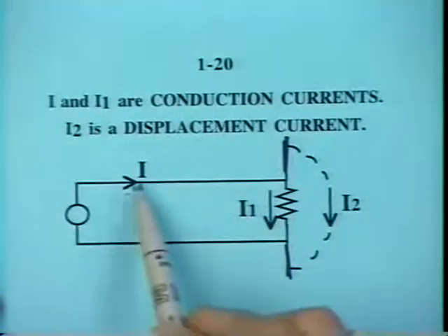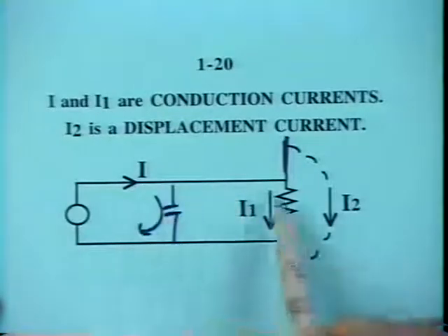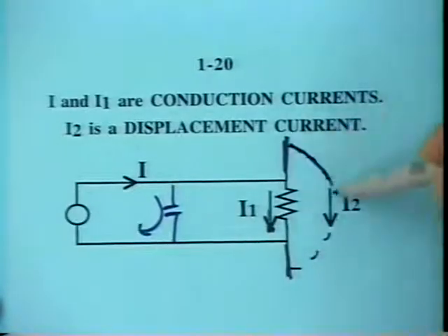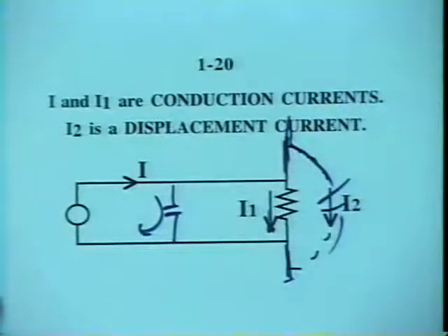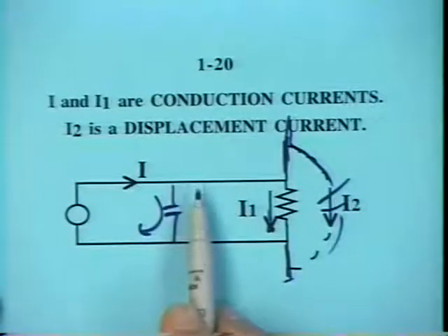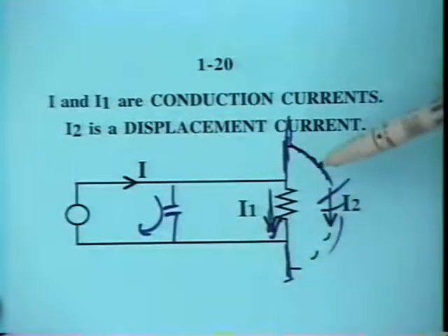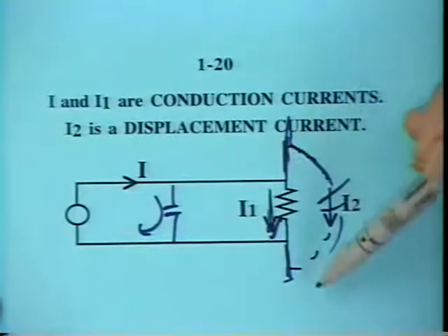Well, then what will happen is this current, of course, now some of it capacitively couples over like that, but part of it will go through this resistance, but a little bit of it will go through this capacitance between the two pieces of metal hanging out there. We call current through a capacitor displacement current. So our intended conduction current splits up into a partially conductive path through the resistor and, unfortunately, a much unintended displacement current path through the capacitor.